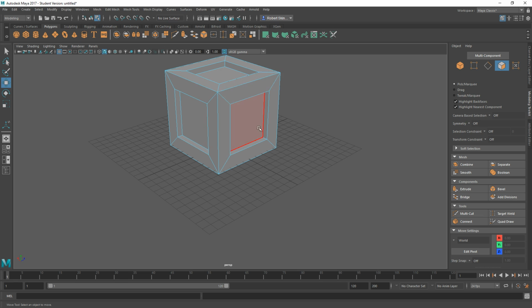So we have these extrudes now, and we have the depth, which is great. This is what we're looking for. But there is a question that you could ask yourself at this point, and that is, do I create that slat out of a separate primitive, another box, or do I model it into the crate itself? In this particular instance, we are going to model it out of a separate primitive. There may be certain occasions where you might want to keep the model as a whole. I've found in my experience that when you're unwrapping, which is a process we're going to go through later on, individual models are much easier to control unwraps for than very dense meshes that are totally modeled together.